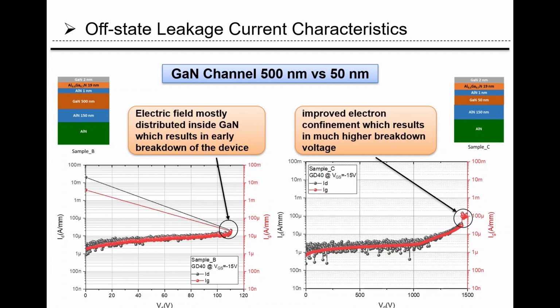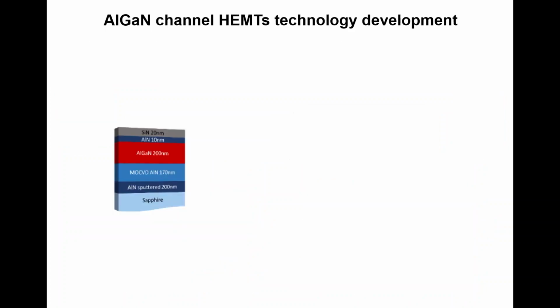So when you see that, you say, we don't want to use gallium nitride anymore. You want to use AlGaN as a channel because you still need a difference in the conduction band. And that's what we did. I'll just go quickly. Instead of GaN, this is AlGaN, 50%, it's pretty high, on the aluminum nitride platform. So, okay, here is a sapphire. It's just for resources reasons, we couldn't have a bulk gallium nitride, but still aluminum nitride sputtered on sapphire, with regrown aluminum nitride.